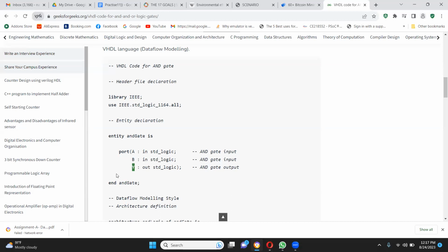Let's say in case there is an uncontrollable error, but the clock is still running. What you need is some external signal to completely reset the flip-flop, even if you are working in a synchronous flip-flop sequential circuit. So in that case, you need an external reset pin also to control the synchronous circuit. Hello? Yeah, I'm still here, sir. I'm listening. Yes. So this is about the entity.